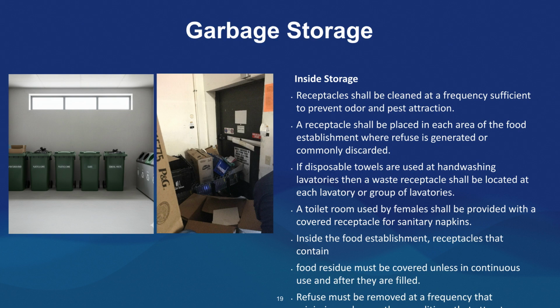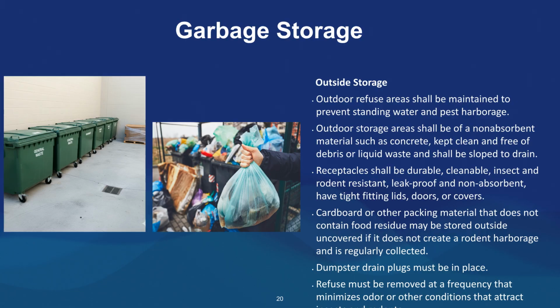Storage areas should be clean, non-absorbent, sloped to drain, and free of debris and liquid waste. Receptacles must be durable, cleanable, insect and rodent resistant, leak-proof, non-absorbent, and have tight-fitting lids. Refuse should be removed at a frequency that minimizes odors and pest attraction.